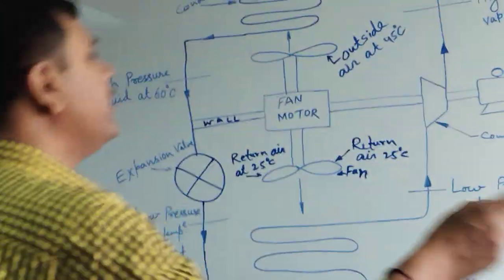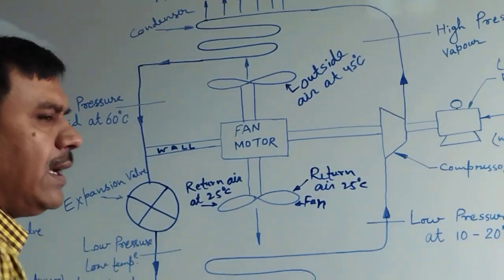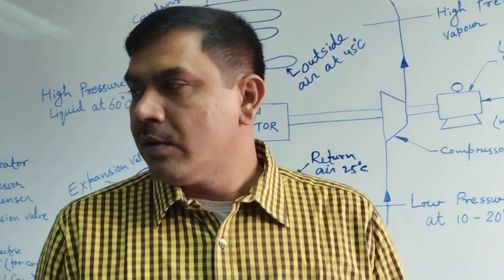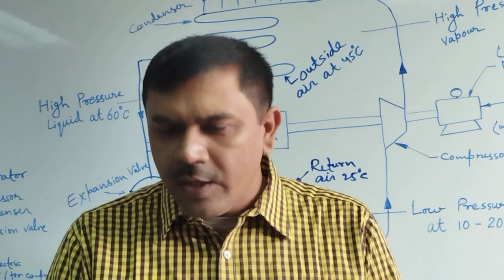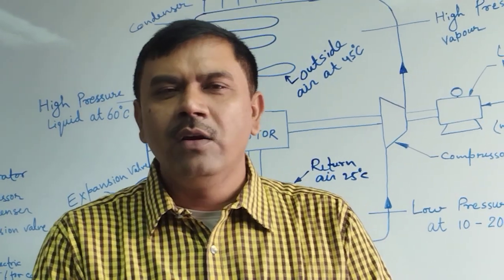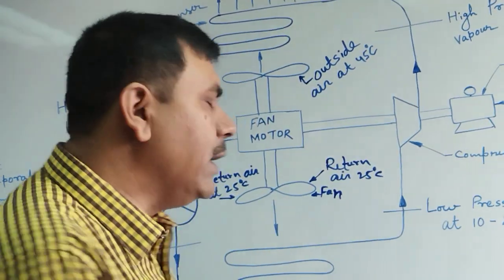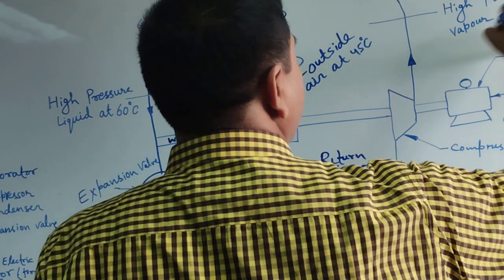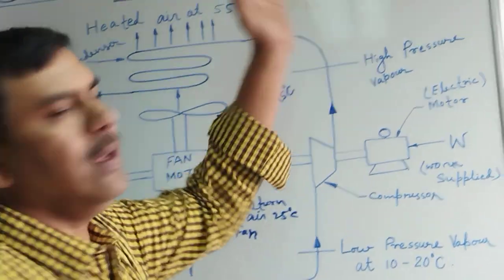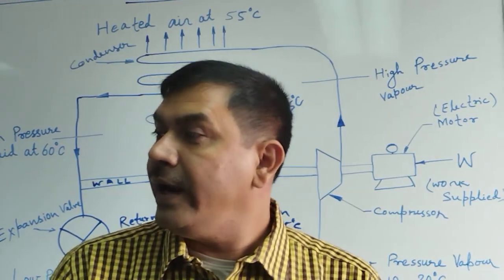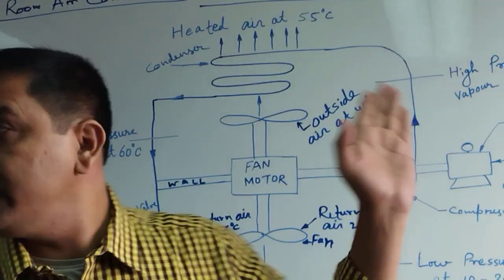Okay. Now the compressor compresses the air. When the air is compressed, what happens? If the volume is V1, it will shorten, so the volume is reduced. Then suddenly its pressure is high. The low pressure refrigerant becomes high pressure refrigerant, and the temperature is very high, about 200 to 300 degrees Celsius.